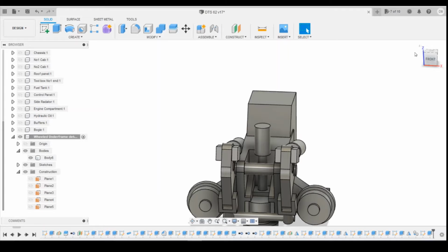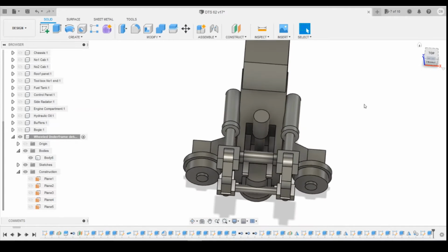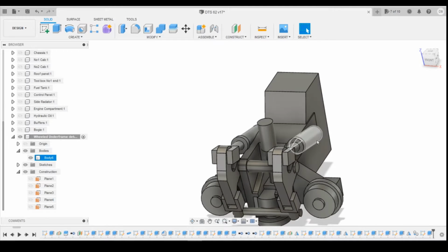That's fixed it. So what's caused the issue there is because we've got this curved section cutting through here. It's not recognised that top line because we didn't draw the line in. We just used the side of the upright here. So that's how I was able to fix it. Just go back in, draw that line across, and that's fixed that issue.